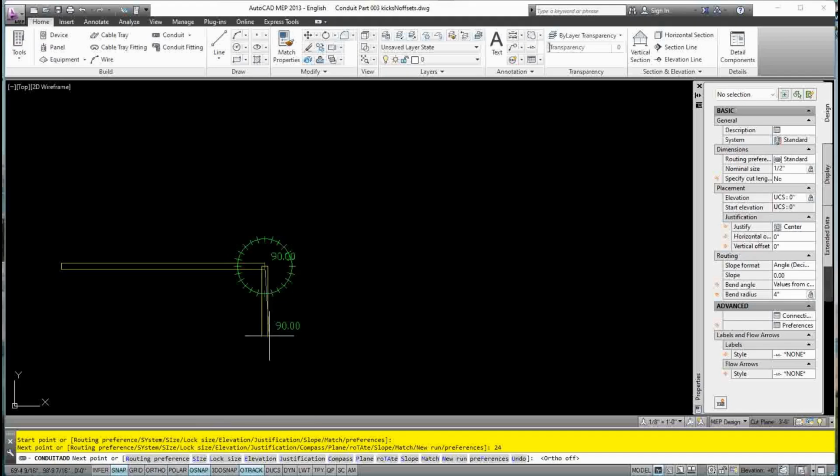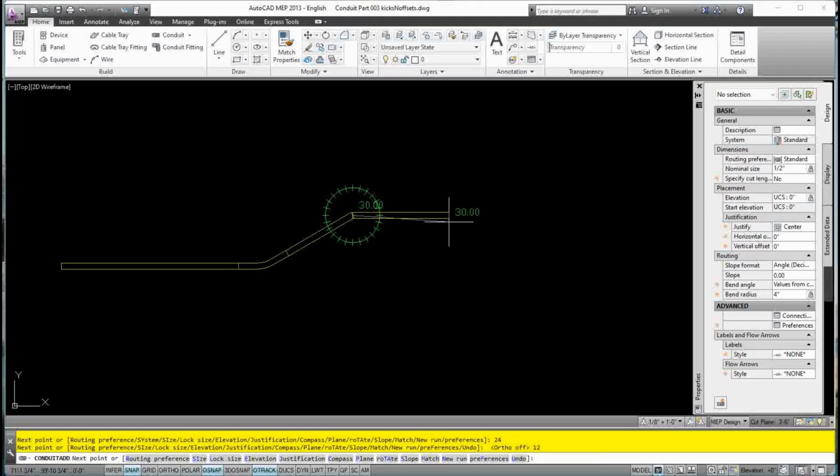It's gray. And you can see the angles that we can choose are 90, 75, 60, 45, 30, 15, and 0 degrees. So I'm going to choose 30 degrees, pull it in that direction, and type in 12 inches. Then I'm going to go 90, pull it out this way, go 12 inches and hit enter. Okay, there we go. Then we're going to hit escape.